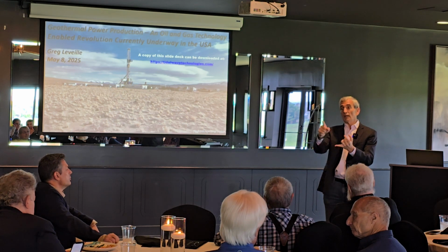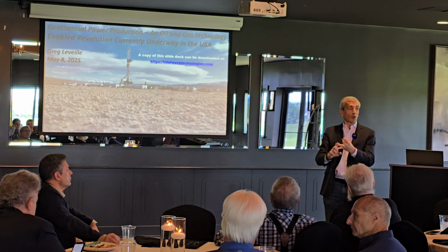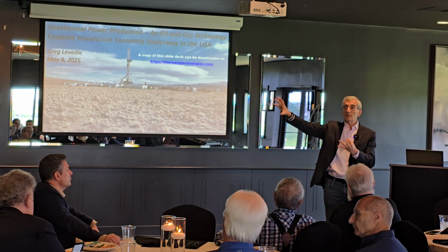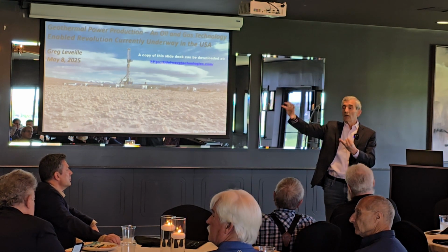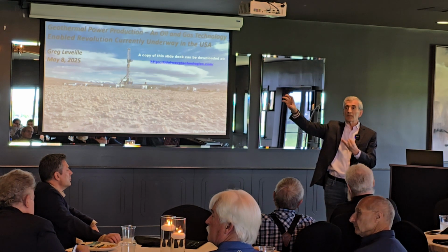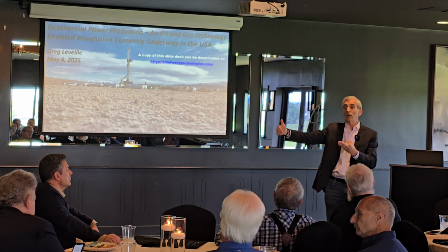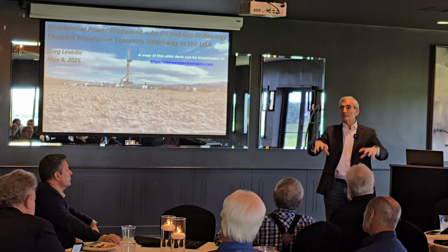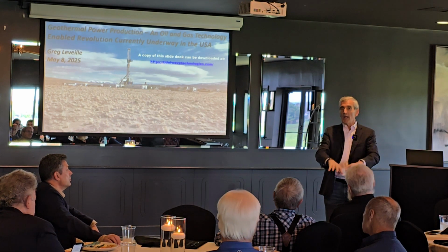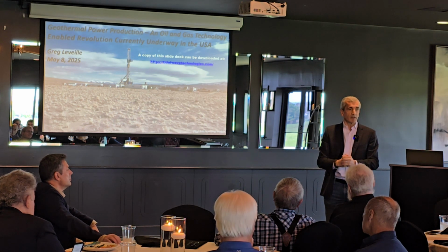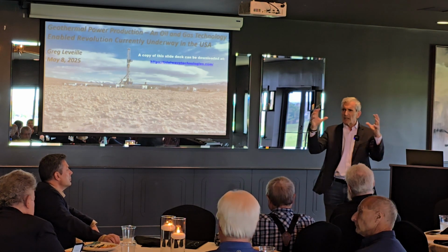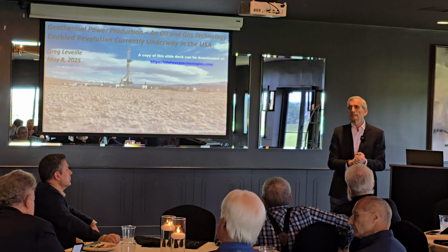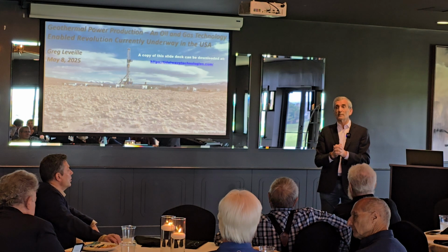So thermal longevity, which is what you're asking about, Aaron. Water losses: if you're moving millions of barrels of water around one of these systems and you're losing 10% of the water you're circulating, the cost of the water makeup is very significant. And then induced seismicity. If you're losing a lot of water, you in Oklahoma, I don't need to tell you about what happens when you put tens of thousands of barrels of water away in the basement. You get induced seismicity. So you don't want to have water losses. You want to design your well field to minimize water losses and maximize thermal longevity. So really, really important topic you brought up.